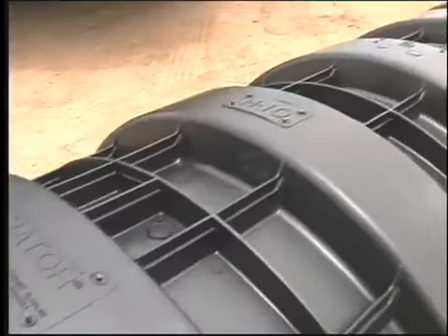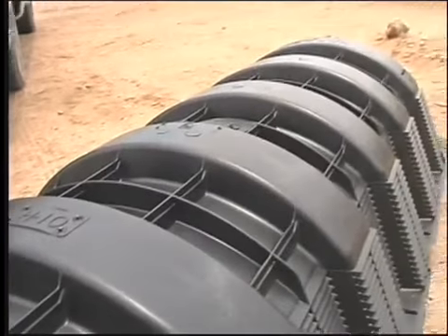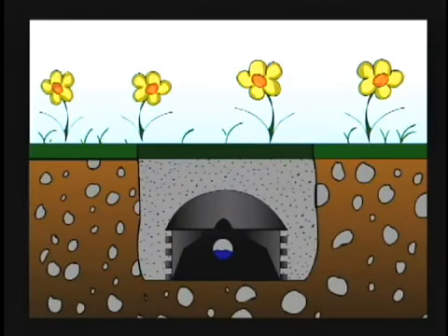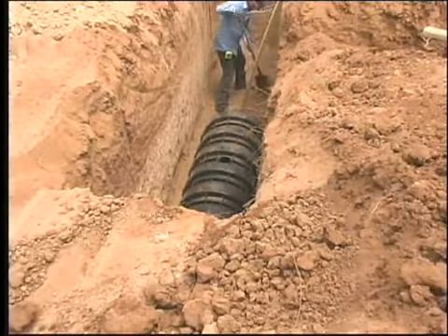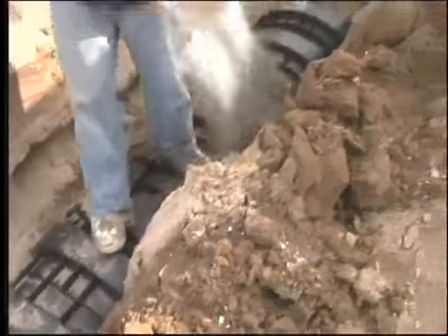Chamber drain fields are quickly becoming more popular than gravel and pipe drain fields. The trench preparation for the installation of chamber systems is the same as traditional gravel and pipe drain fields. However, there must be no slope on the trench bottom.